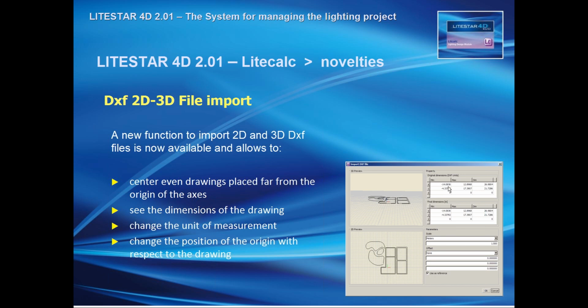X, in this case, for this drawing, is at 26.9 points, the DXF units. And if we convert into meters, it will be 26.8 meters. But it is up to the designer, up to the user, to verify if the dimensions are correct. So we have to verify if this drawing is really 26 meters coming from one point to the other in X and on Y.